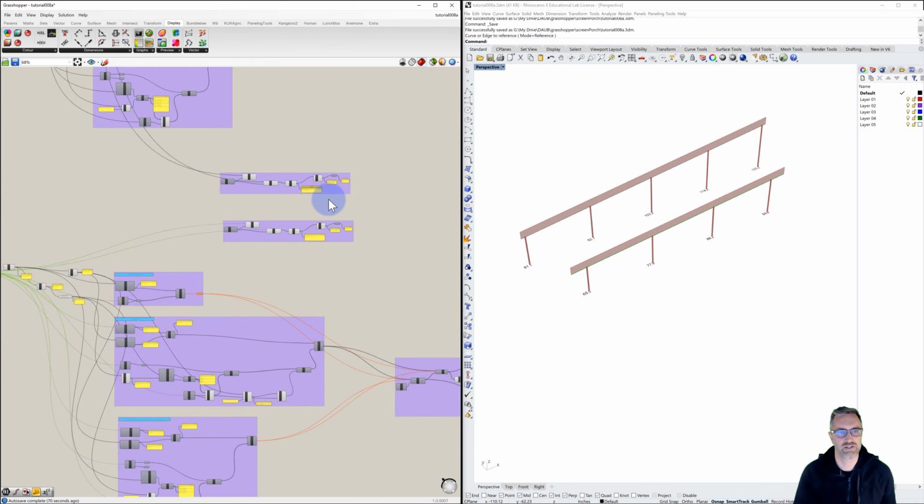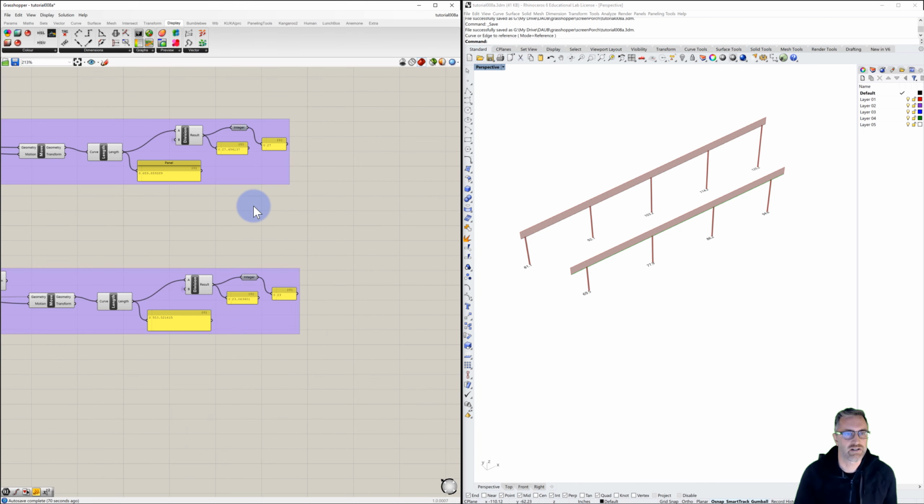Okay, so now using these two, what we'd like to compare, let's even zoom in a bit, we can see that one of them has 23 divisions, the other one has 27 divisions. And I don't want to get too into construction logics here, but for what we're going to do, rather than keep the spacing consistent in terms of 24 inches or 16 inches and have all those parallel, you would want to do that if you were working with plywood sheets, and if these weren't parallel, you'd end up cutting every single sheet, and there would be other implications for this.